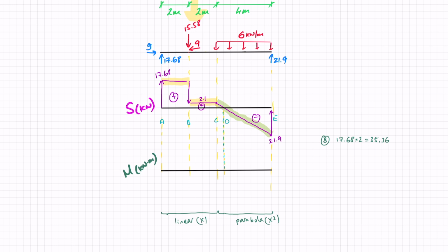If I don't want to do calculations and I don't want to draw a cut, I just want to look at it. Let's just look at it in this way. I've got a diving board, an upside down one, and somebody standing here, right? This board would take on this shape, wouldn't it? It would go like that, meaning that on this side, the board would get longer, and on this side, it would get shorter. The side that it gets longer is my tension side, and that is the side I want to draw my moment on.